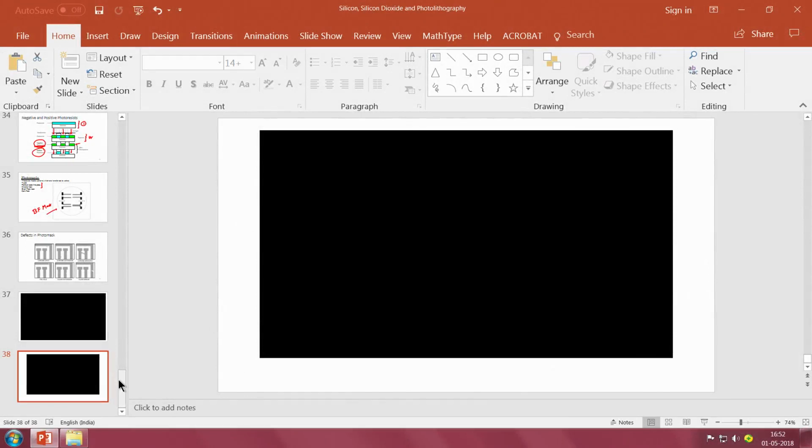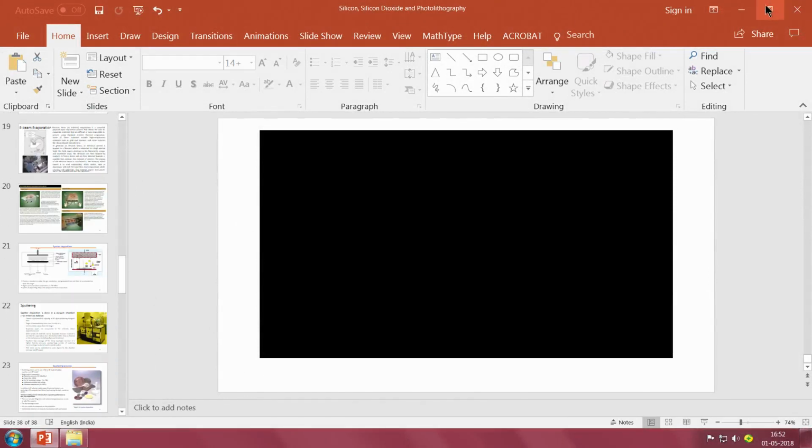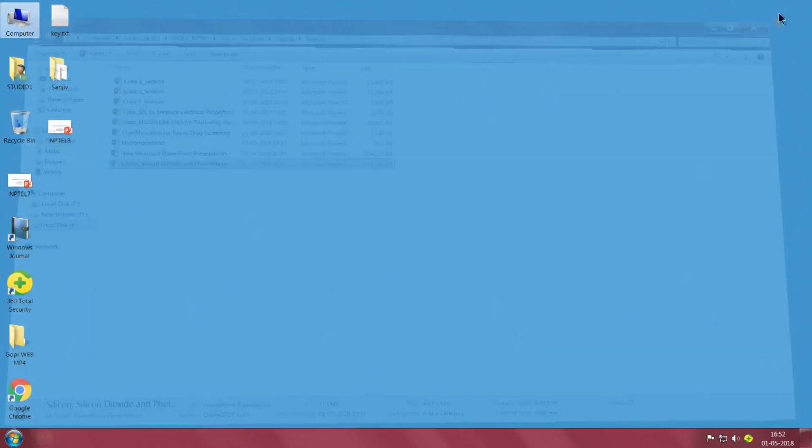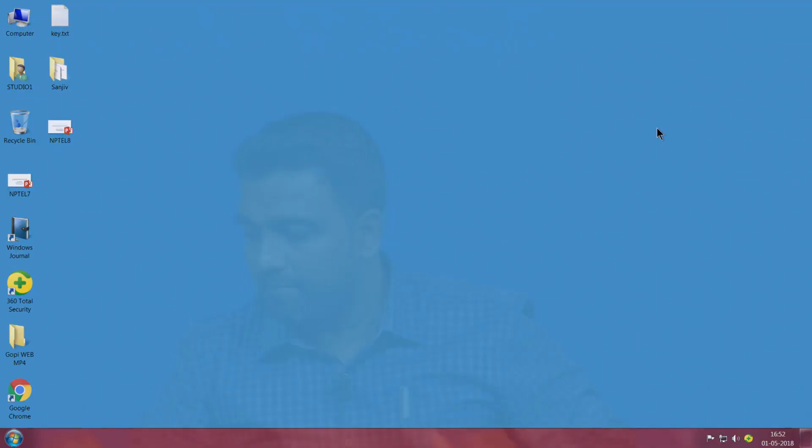Okay. So, if you now see what we have learned, I will show it to you on the screen here. What we have learned today is a step called photolithography. In the last two videos, what you have seen, one is an automatic mask aligner. You have to load the wafer, it will perform everything, a robotic arm will take the wafer and then it will perform the photolithography. In the second one, you have seen how you can perform front to back alignment, how you can align the wafer, how you have to align the mask, what is the procedure.